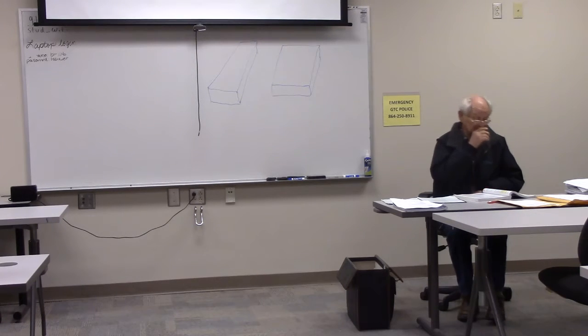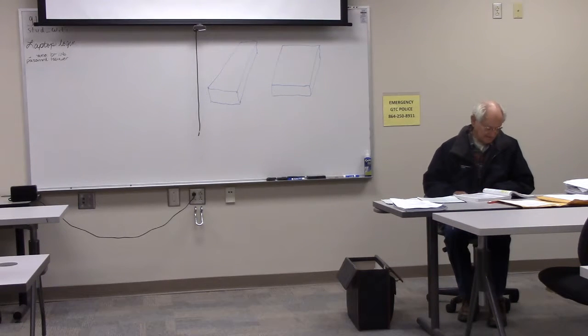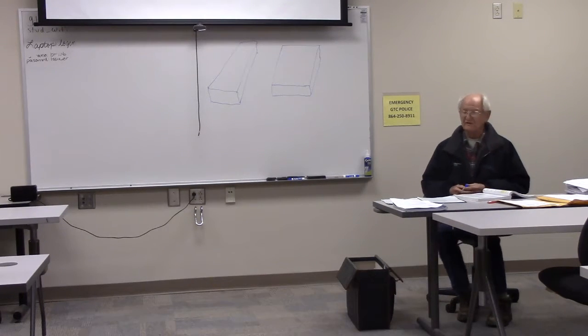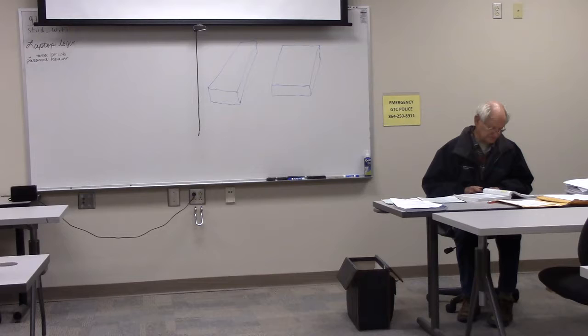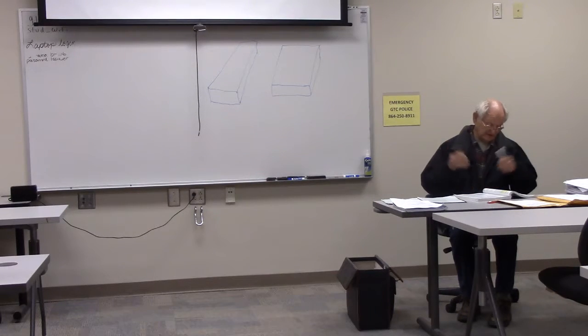Sizing, pull, and junction boxes. Pull boxes should be as large as possible. And I agree with that with some reservation. You could put one up there that'd be much, much bigger than it needs to be, but they're talking about within reason. Workers need space within the box for both hands, and in the case of larger wire sizes, workers will need room for their arms to feed the wire.